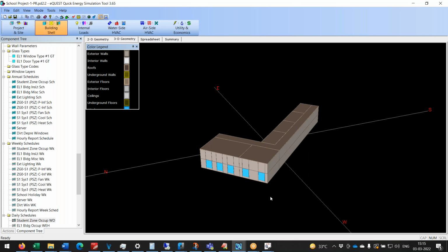Yes, for VRF and split systems, unfortunately, they do not have an inbuilt provision for fresh air. You have to provide TFA.